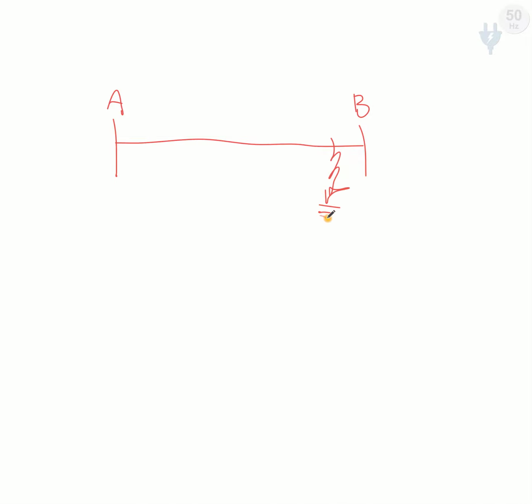It means some faults occur in this transmission line which are transient in nature and disappear immediately. So it happens and then goes out. Mostly this type of fault occurs due to trees and vines in overhead lines, and maybe due to insulation deterioration of underground cables.